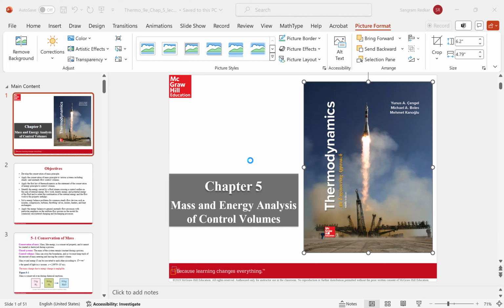For example, if you have a spherical control volume, imagine that you have mass coming in from 3 different directions and mass going out from 2 different directions. When I'm going to write down the energy at in and energy at out, I would sum the energies at those 3 inlets and I would sum the energies at those 2 outlets. That is how I would analyze this control volume. Does everyone understand this?